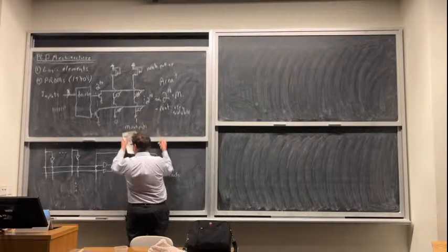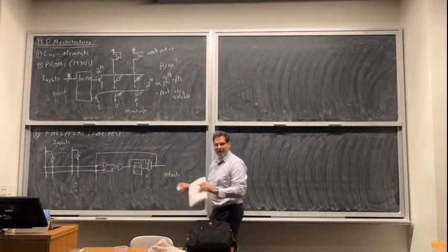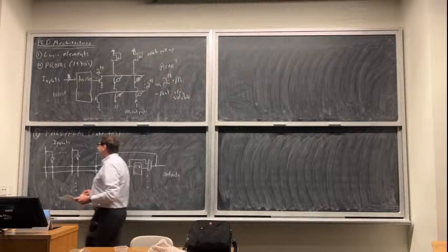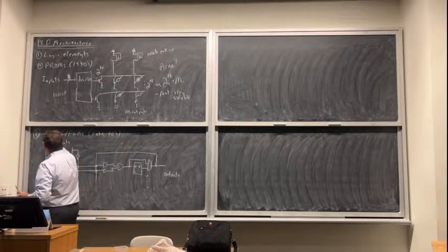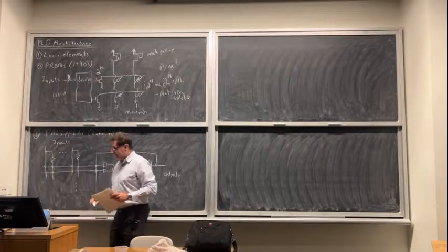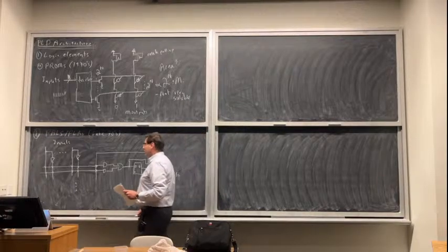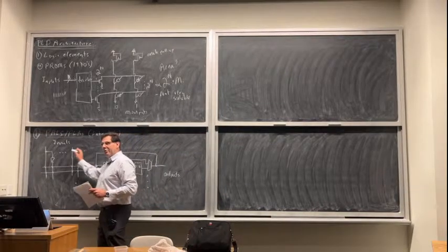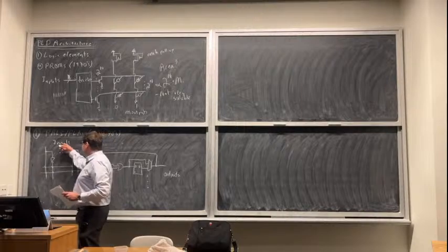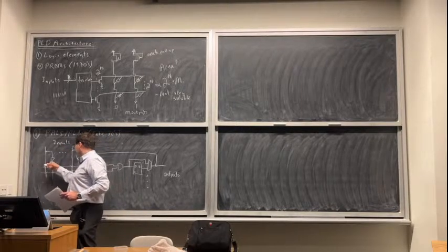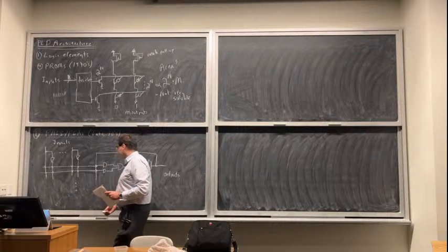Okay, and then I've actually drawn the second thing that people came up with. The second thing people came up with, they confusingly came up with two very similar names for slight tweaks on this: programmable array logic or programmable logic arrays. They both basically look like this. You have a bunch of inputs. You complement the inputs, so you get both the true and the complement form of the inputs available.